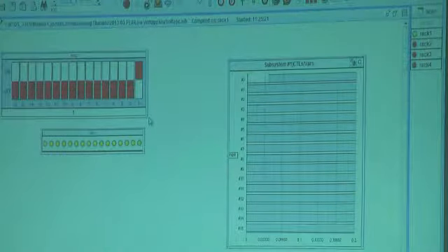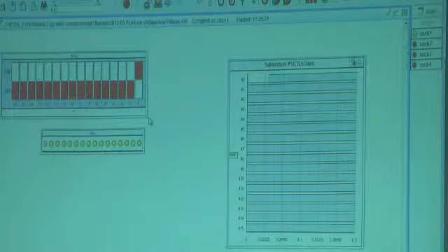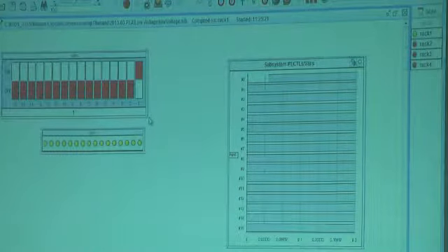Be careful, we don't usually want to apply a voltage to the input because we'll burn that resistor that's there if the voltage is too high. So you guys can build a simple case like this and try shorting the contacts or doing the loop back.